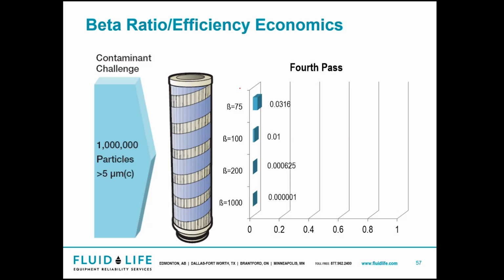So for a circulating system, like you would see in an automotive engine or a haul truck engine or whatever, you're filtering the oil up to 15 times per minute. So think of how quickly you're filtering out all those contaminants. And that doesn't even take into consideration diesels with spinner filters or anything. This is just your typical run-of-the-mill engine oil filter.